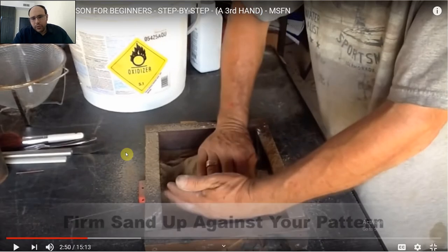So as you can see, he's putting sand. This is a conventional sand with some other additive material. We could add some water, but only a very small amount, in addition to other material that could be added to give it the ability to be shaped, so the particles of the sand stick together to form a shape. So what he has done here is put fine sand grains very close to the pattern to give the final product a very smooth surface and good surface qualities.